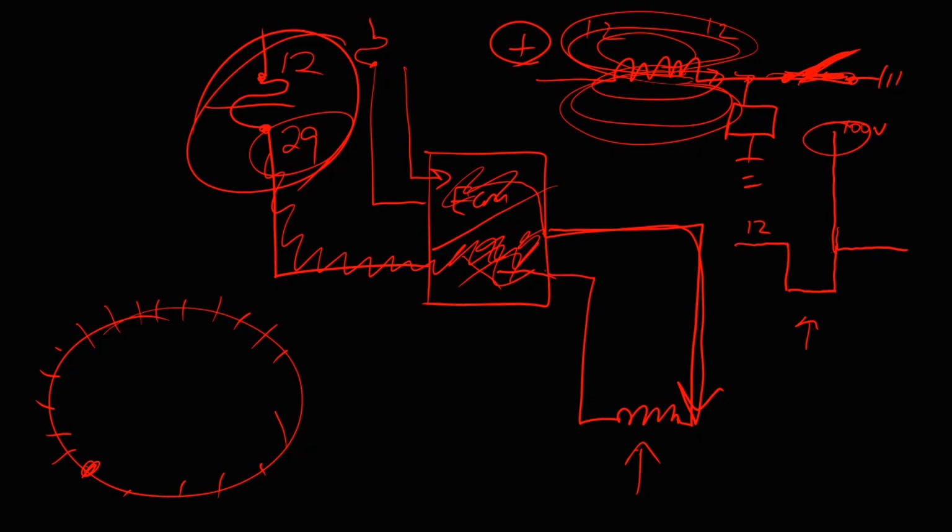Here's the tie-in. If you're measuring a fuse and you see 12 volts and then some other random voltage that you know the fuse is blown, you're like, that shouldn't be there, right? We know fuses are blown, 12 and 0, that fuse is blown. Test light, 12 and 0. Or light and no light. Any other voltage you see is either A, a bias voltage, which I just explained to you, or B is some kind of crazy backfeed like I'm seeing right here.